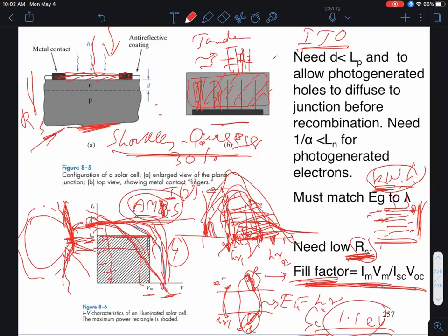And in the earlier days of solar cells, the efficiencies were not high enough. In fact, the total integrated energy output that you could get out of the solar cell was initially lower than the energy input to make the solar cell, and then it became comparable. But now, with improvements in solar cell efficiency, you can get silicon solar cells with an efficiency of, say, 25% or so, which is close to your Shockley-Queisser limit. Now, the net integrated output is much higher than the energy input required to make the solar cell, okay? And in many cases, the cost of electrical output from solar cells is, in some cities and states, lower than the cost of generating electricity from fossil fuels. Okay, forget about climate change and all that.